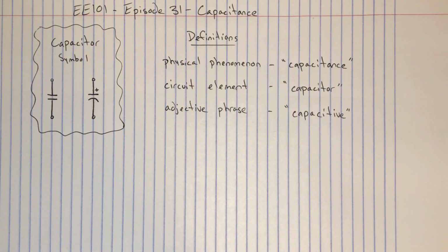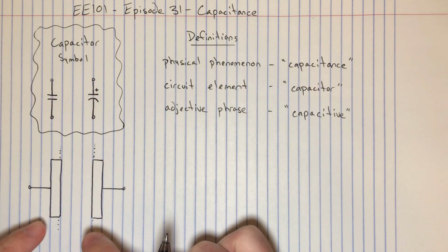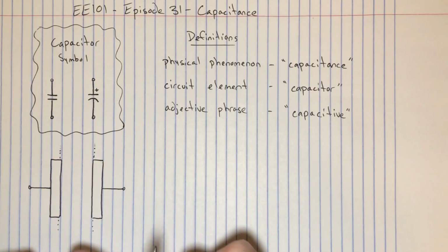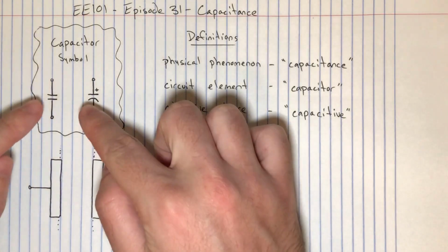Capacitors are created by separating two conductors with an insulator. The insulator could be one of any number of materials like air, polyester, polypropylene, mica, etc., and is called a dielectric. The most common structure we use is called a parallel plate capacitor, and it looks something like this. Imagine the two parallel rectangles to be the conductors and the space in between to be the insulating dielectric. And these lines and dots I've drawn off to the side are just our ideal wires from our circuit elements.